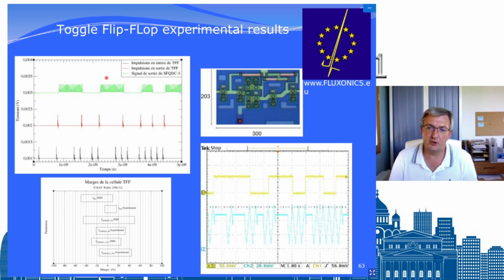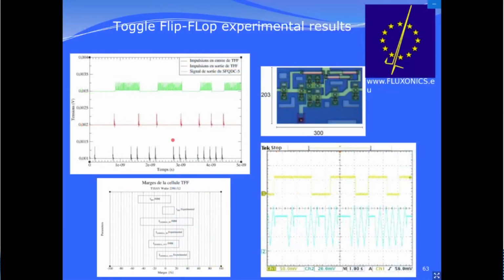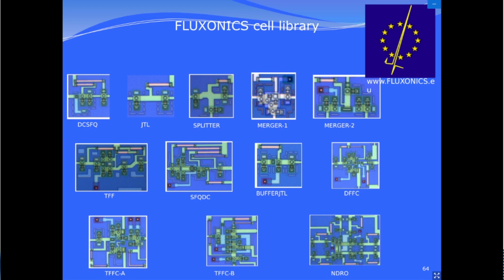Of course, you cannot measure the pulse, but you can make a cell which has a non-zero value when you have an input pulse, and which goes back to zero when you have another pulse. So when you have two pulses, here it's zero before, here it's a 1, here it's 0. So when you measure this signal, which you can see on an oscilloscope, what is important is not the value here, it is the time when you change, because then you know you have a pulse, and you can check if it's okay or not.